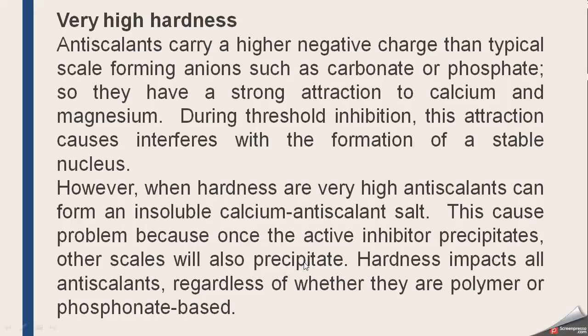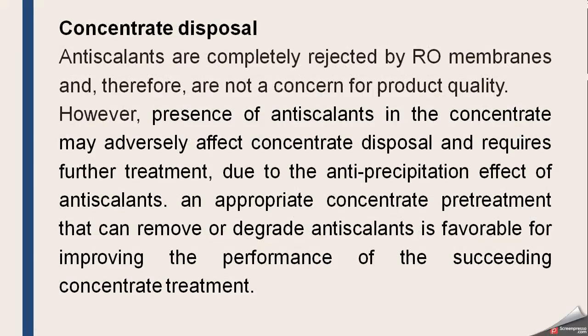Because when the inhibitor starts precipitating, instead of capturing those ions and keeping them suspended in the water, if they precipitate, then other scales will also precipitate, and hardness impacts all antiscalants regardless of whether they are polymer or phosphonate based. And the final important issue is the concentrate disposal, because the antiscalants which are used to inhibit the scale